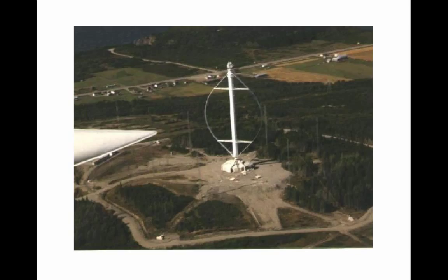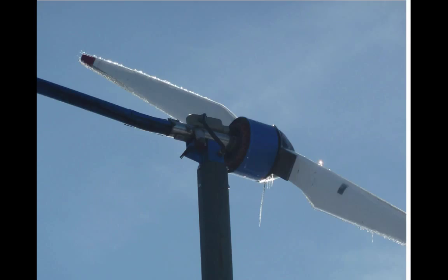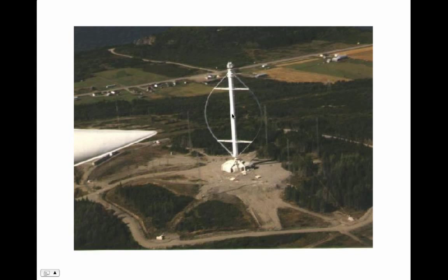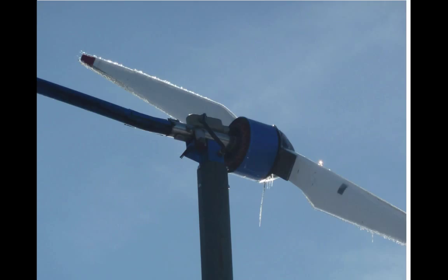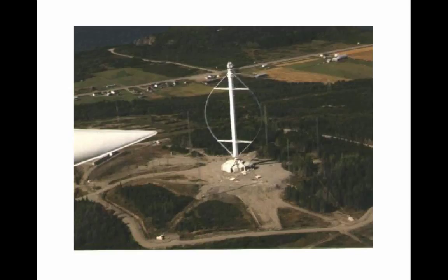There are many different kinds of wind generators. This kind is called a horizontal axis wind turbine because the axis it spins in is horizontal. This is called a vertical axis wind turbine because the axis it spins in is this way. And this one spins around like a giant egg beater. There are many, many different kinds of experiments in wind turbine design, but most have settled on this horizontal axis, 2 or 3 blade, and generally 3 bladed is better, wind turbine design.